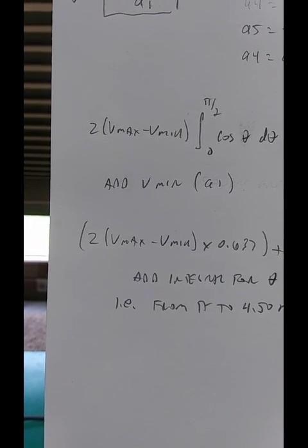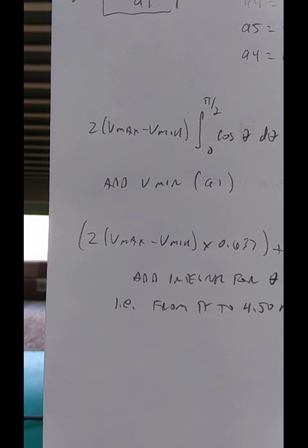Then add in the V min, which is 1000 volts from the tube data sheet. That's the A1 area. The integral above finds the average value of the plate swing. That's added to the minimum voltage, and that gives the total average voltage for that plate swing, and that cannot be found by any other method. Any other way of doing it will result in gross error.